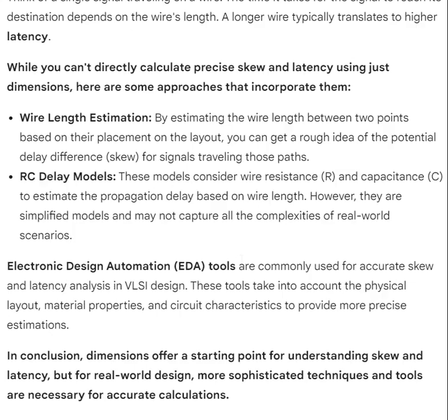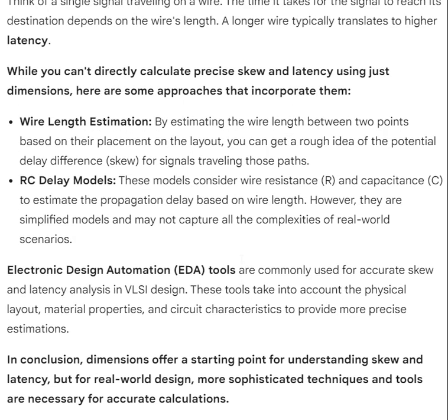Electronic design automation, EDA, tools are commonly used for accurate skew and latency analysis in VLSI design. These tools take into account the physical layout, material properties, and circuit characteristics to provide more precise estimations. In conclusion, dimensions offer a starting point for understanding skew and latency, but for real-world design, more sophisticated techniques and tools are necessary for accurate calculations.